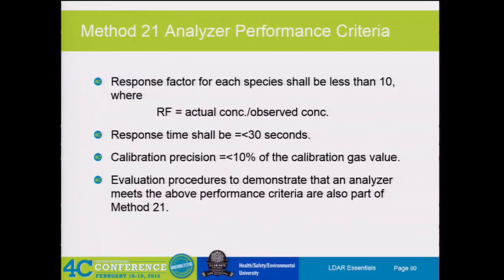Response time shall be equal to or less than 30 seconds. So with this, as you all know, and this was another thing that came up just recently for us, on your heavier product ends, it's going to take longer for the machine to respond to those, correct? So by just taking a little bit of time with your technicians and your site and actually looking at the product side so that they understand, when I come in to do Method 21 on a heavier end unit, I should spend a little bit more time during my survey.